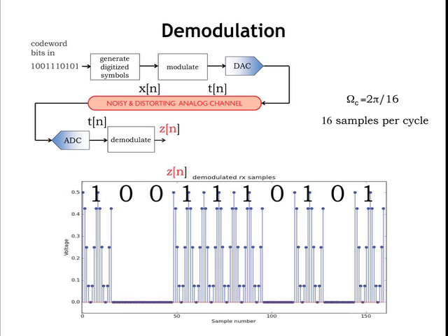Okay, so this was a 0-1 waveform that we transmitted, but we're demodulating it using a scheme that could have actually handled a signal that went negative as well. But this example doesn't have a signal that goes negative. It was the one that I showed you earlier, but you can see that the average value here is picking out exactly what you want. So your challenge now is to get rid of the double frequency piece.